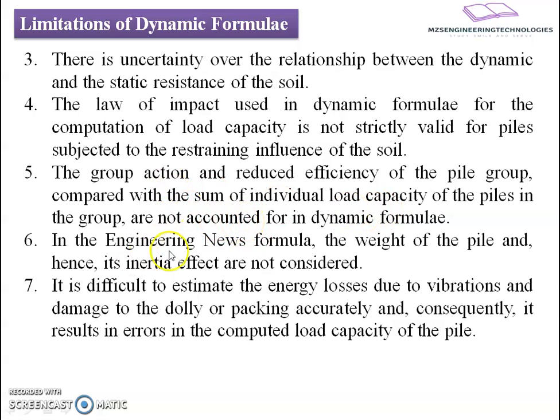In the engineering news formula, the weight of the pile and its inertia effects are not considered. It is difficult to estimate accurately the energy losses due to vibration and damage to the dolly or packing, and consequently it results in error in the computed load capacity of the pile. Yes, there is uncertainty related to the damage observed in shock resisting elements like the dolly or packing, and thereby it may give uncertain results.